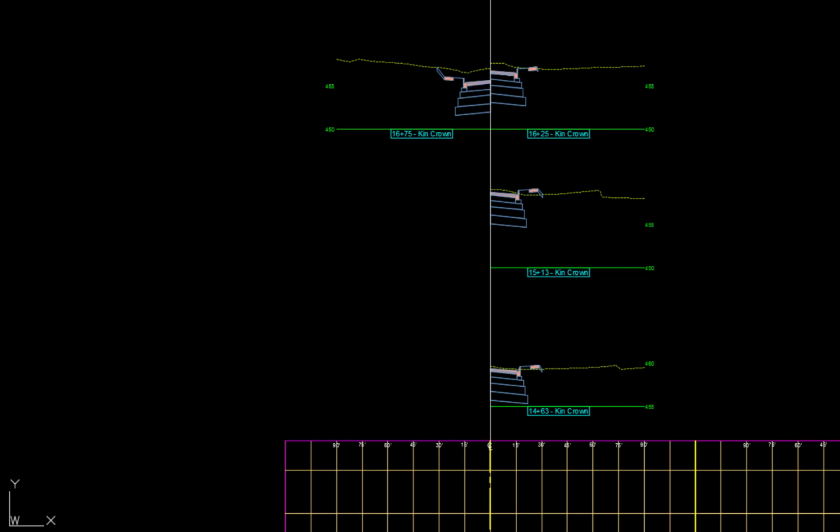2 columns of combined left and right driveway profile section views will be located onto each grid sheet. 1 horizontal row in the combined column may contain a single left or right section view or both a left and right section view. Each combined column will contain 5 or 6 horizontal rows of left-right section views depending upon the spacing between the views. The section views will be inserted into the grid sheet from bottom up in ascending order. Use the Move command to insert the driveway profile section views onto the grid sheets.